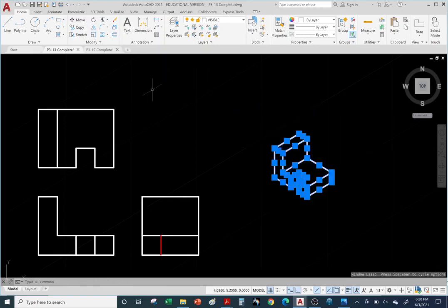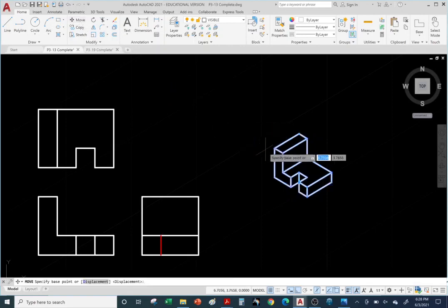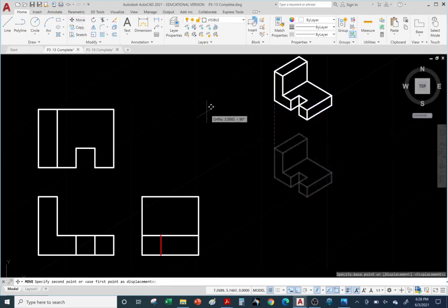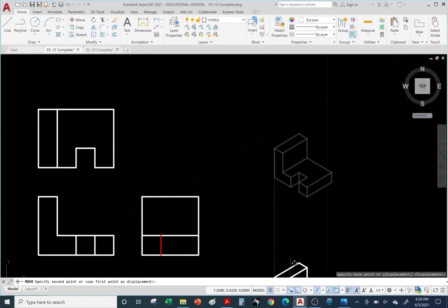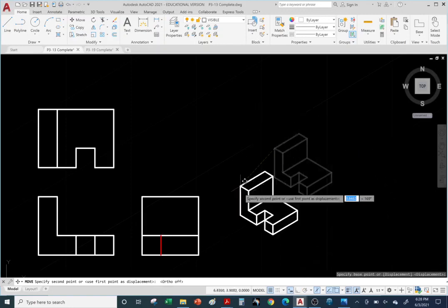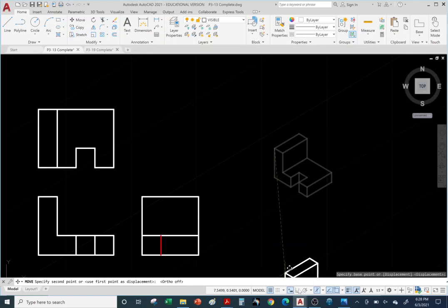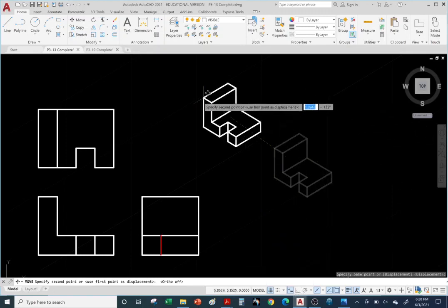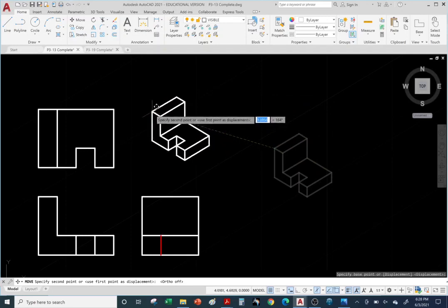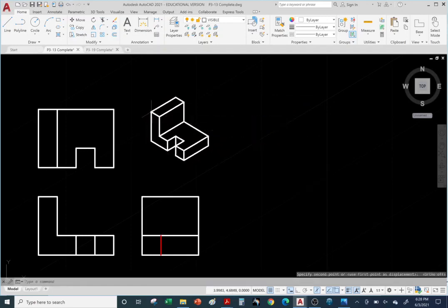So I'm going to go ahead and insert and lasso the part, click move, grab it from any corner. And let me turn off object snap. Turn off object snap. As you can see, my mistake, ortho mode. Ortho mode is off. So now I can go ahead and place it. As long as there's room, it doesn't look crowded, that's a good spot for it there.